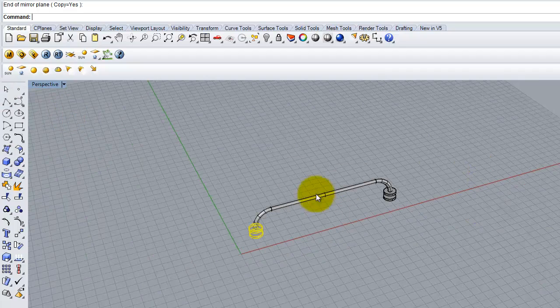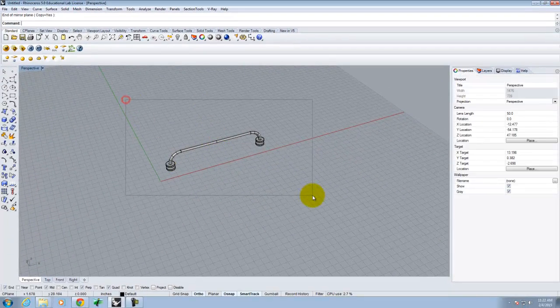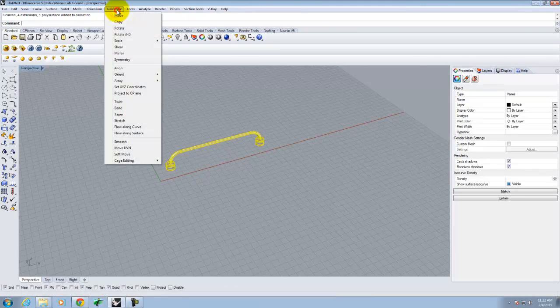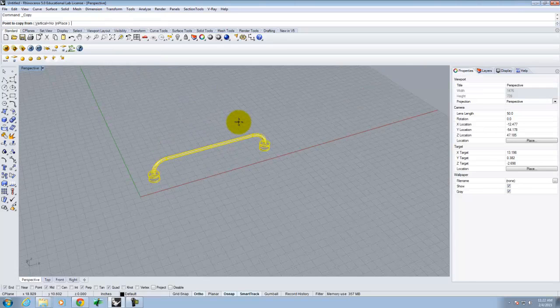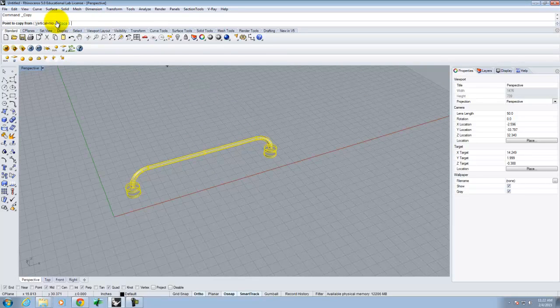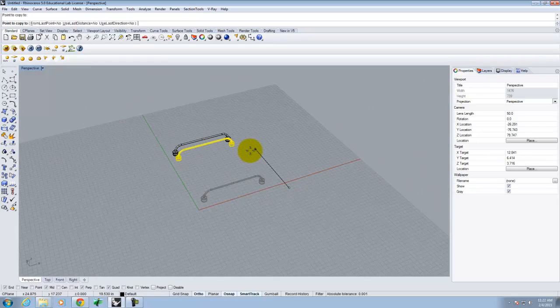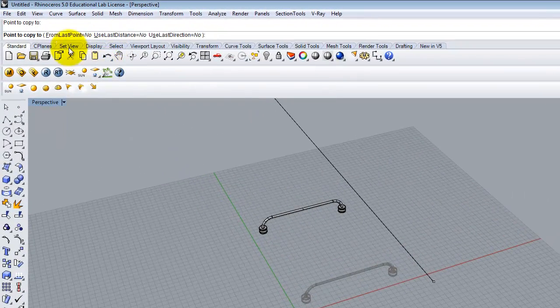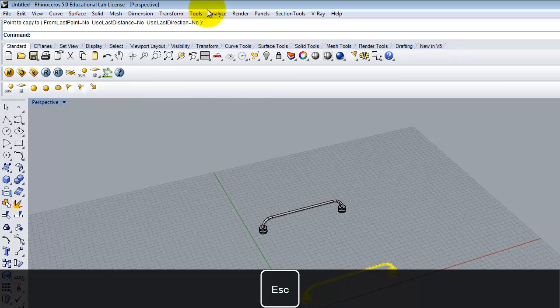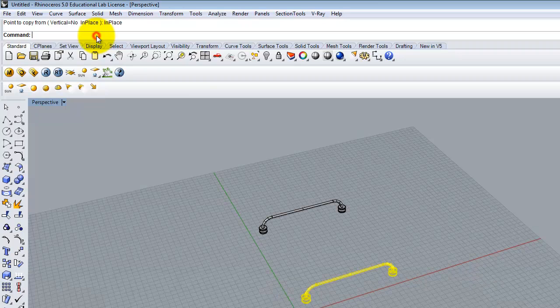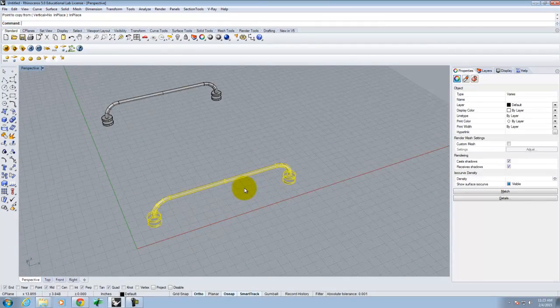this because I want these two to intersect at 90 degrees. So let me take this, and I'll go to transform and then copy, or type copy. And I'm going to specify, this is a trick. I don't have to do it this way. I can copy and paste it like this, where I click a spot, put it over here, and then I'll combine them together afterward, right? Or when I do that initial copy, I could specify in place, and when I specify in place, it makes one copy exactly on top of the other one, right? Then I can come in and I can say rotate.